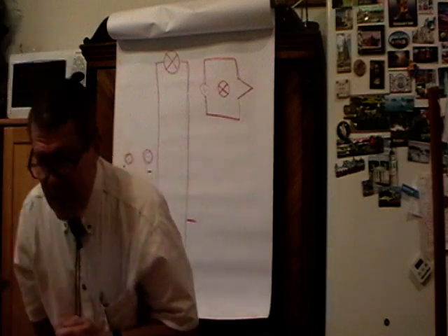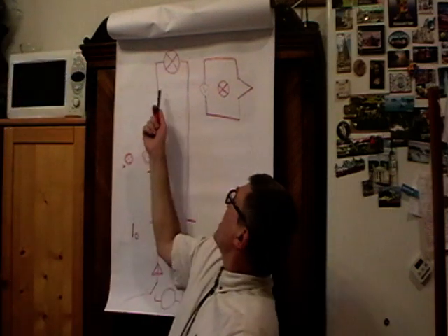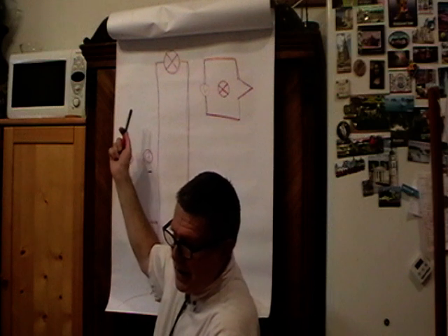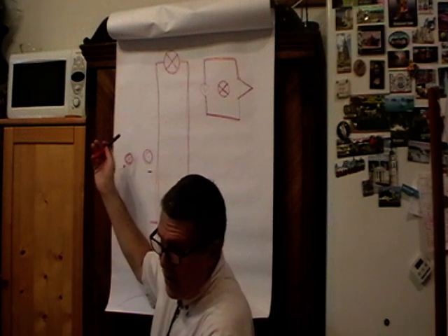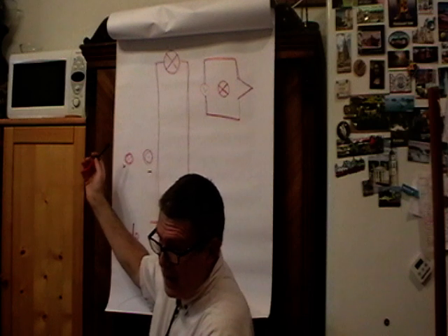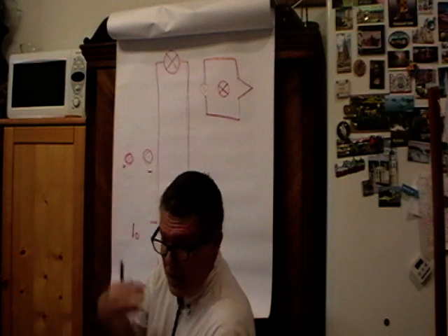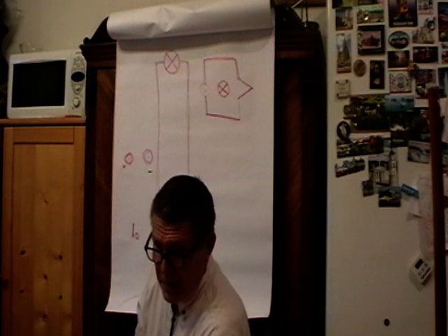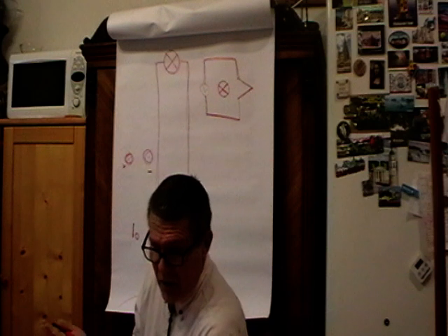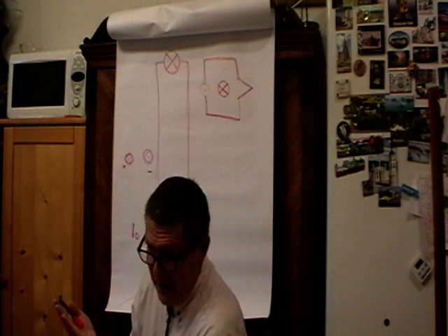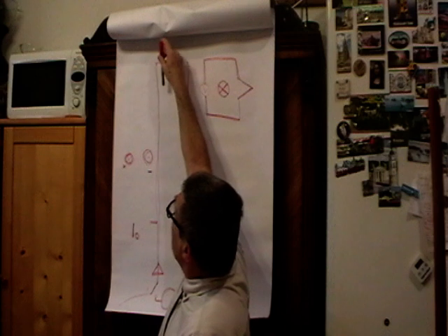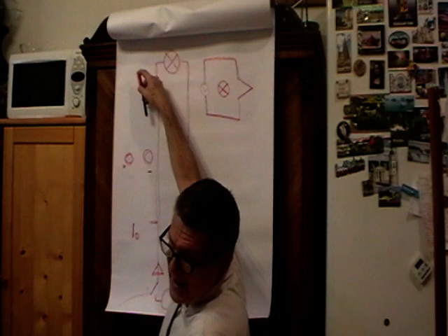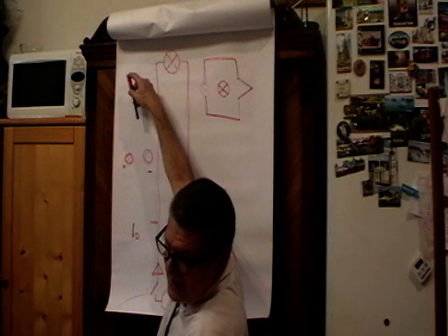But if we have a positively charged conductor and we want to set the voltage to zero, we have to exhaust the charge out of it, because for zero voltage there should be sitting zero charge on the conductor. Which means that the reflected wave has the same direction of current and an opposite voltage.